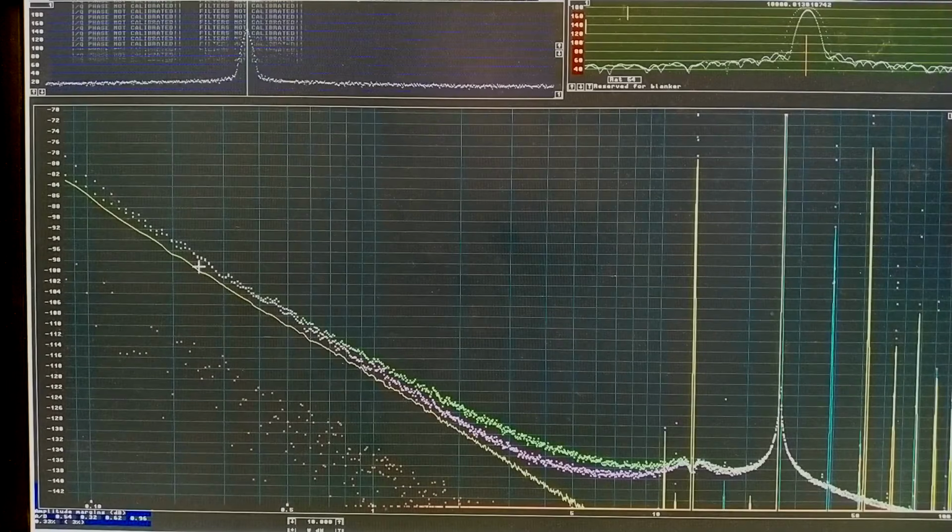It means all 3 oscillators have the same noise level at this frequency offset, and that common noise level is minus 99 dBc per Hertz. And the curvature here is noise from the Schottky diode mixers, I think, and they may be different for the 2 channels, so I'm not sure that the Wenzel really is more noisy than my channel 2 oscillators.